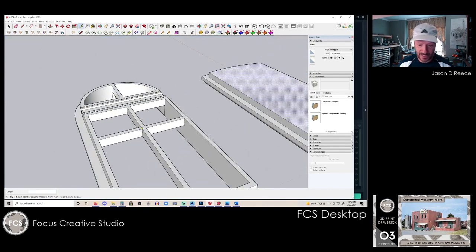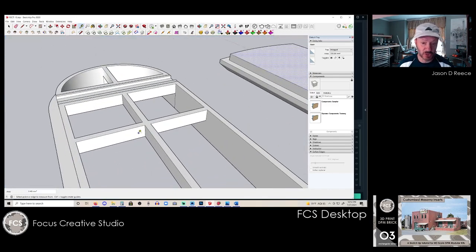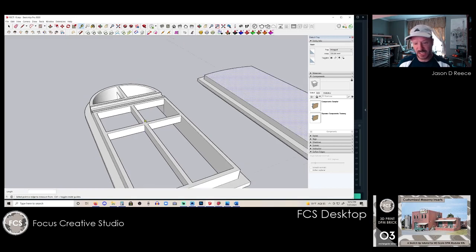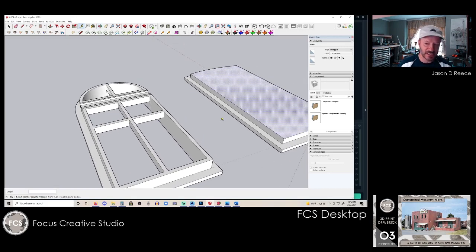You can do 0.4, like I said. I'm not going to do it. It's 0.5. It works for me. The prints come out consistently great every time. I've set the depth on my mullions to 1.2. There are plenty of other people out there doing 0.6, 0.8. Again, this comes down to support placement, consistency, and getting a good quality print every time.